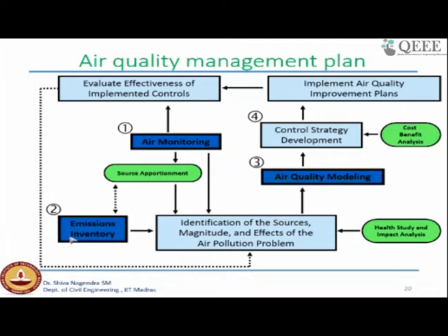You can also do another exercise, which we call an emission inventory. Yesterday we learnt about quantifying emissions using an emission factor and an activity. You can know the different activities happening in a particular area, and if you know the emission factors for all those activities, you are able to quantify which source is contributing significant emissions.